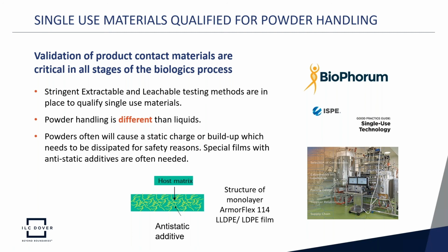Following the BPOG extractable and leachable protocol, looking at the guidance that we get from ISPE and the single-use technology handbook, we really look to see how do we choose the right material. But again, when we're handling powders, this is a different situation than handling liquids.